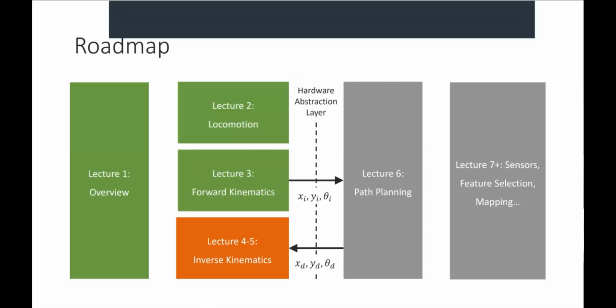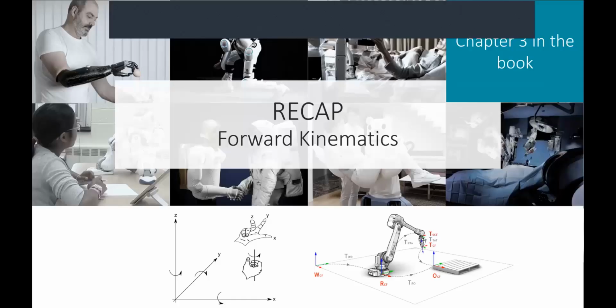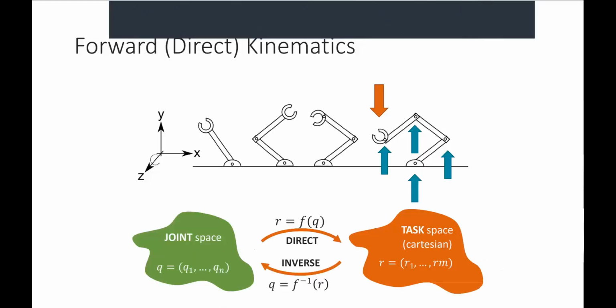Okay, great. So today we're talking about inverse kinematics and feedback controllers. And so just as a very quick whirlwind recap of our forward kinematics and our introduction to this material, right? So we've been talking about essentially going through this transformation. So going from a configuration in joint space, so I picked my motor angles, and then getting out some kind of location in the real world or Cartesian space. And now we're talking about, I've got some location in Cartesian space, and I want to get back to some kind of joint configuration for my robot.